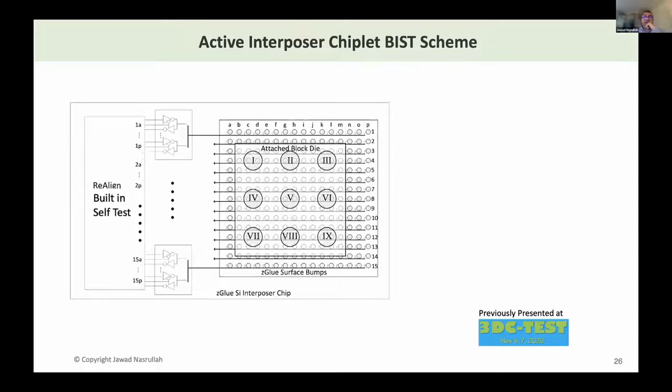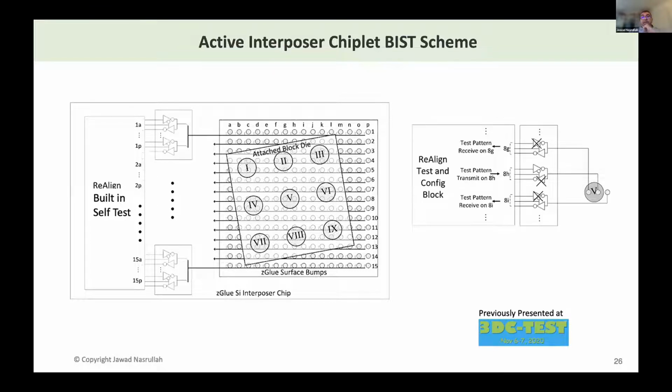So here is an example of one of the tests. This is like 5-6 years ago, and we were extremely worried about backend factory's ability to assemble things nicely. And this actually ended up being much less of a problem because solder is great in terms of pulling everything together, but it's going to become problematic again with copper to copper hybrid bonding. So you may end up with situations where assemblies have some strange issues. That was one of those.